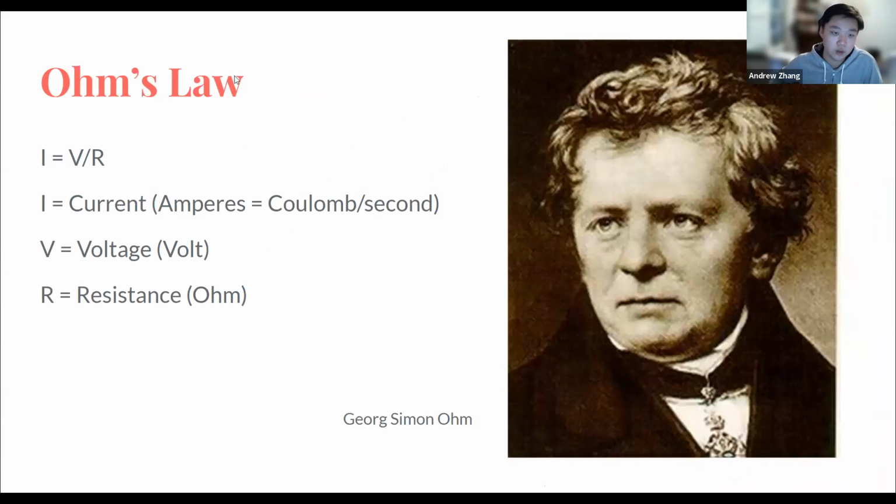And then Ohm's law combines all three of them with this very succinct equation. Very beautiful. You can see all of the properties we talked about, like voltage. More steepness means water flows faster, so more voltage means current is greater. So you can see that they're proportional, whereas resistance is inversely proportional to current because it's over R.